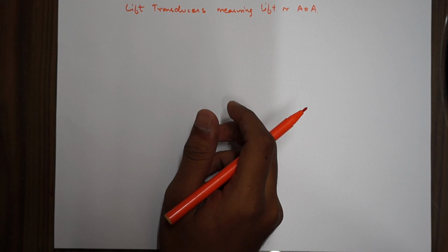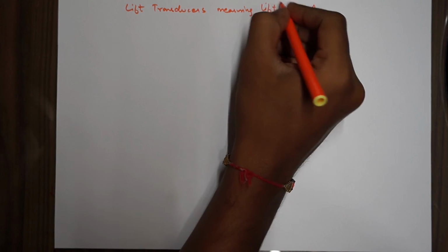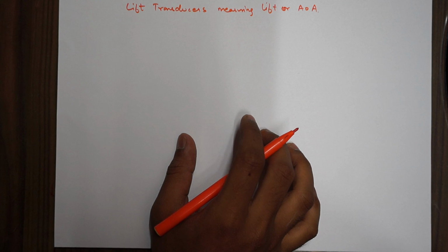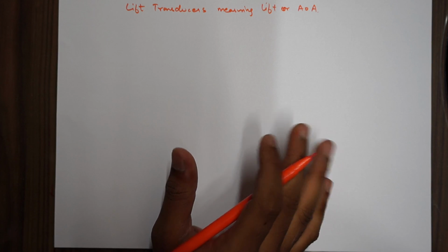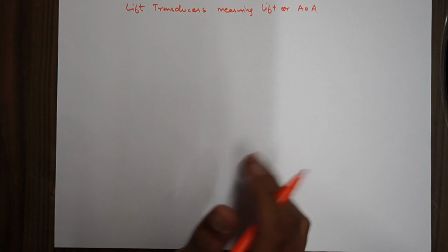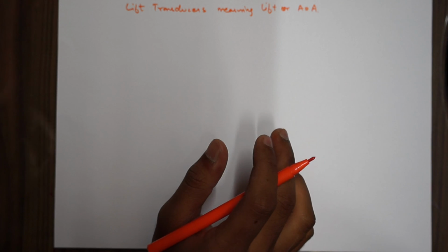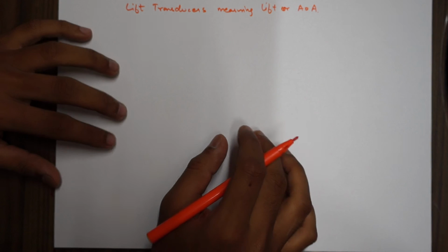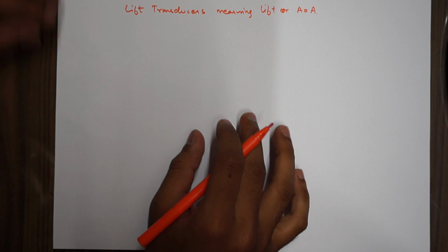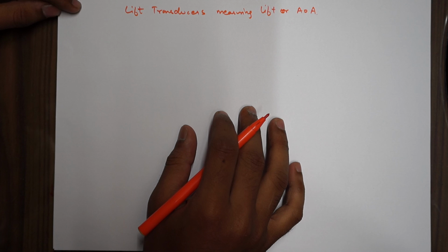It measures the lift or the angle of attack by electrical sensors, and it serves also as a stall warning system, which converts pressure energy into electrical signals and gives an input into the cockpit.